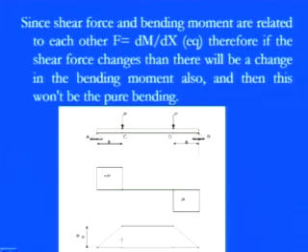So, you can visualize this in the bending moment diagram. This bending moment is P into A, as we discussed, M equals P into A, which has a constant value in this particular section, and these things are there due to the shear forces. So, this is one example in which there is a condition of pure bending, but it is also combined with certain kinds of shearing stresses. So, our main focus is to see, if we have this kind of loading, how we can conclude the shearing altogether with the bending stresses.